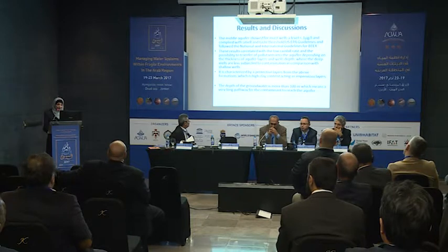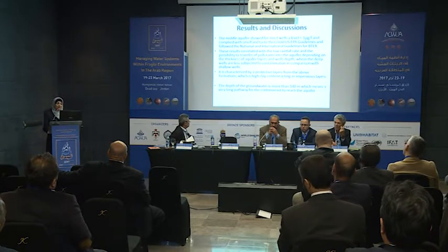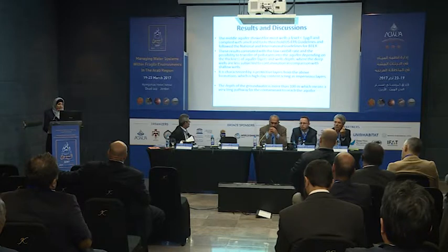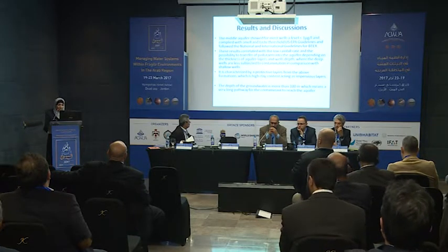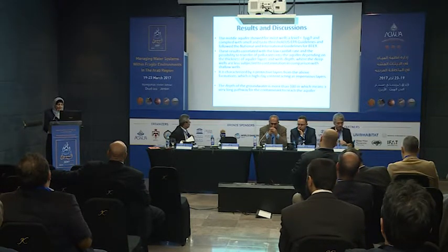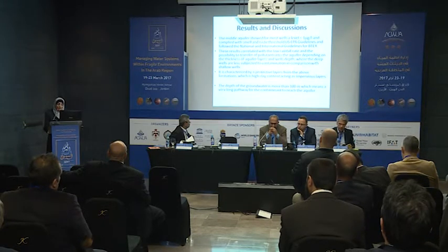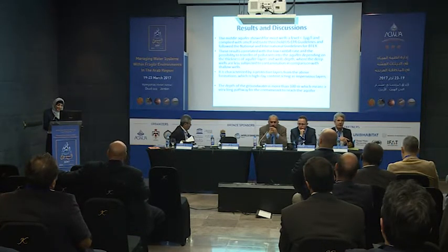Also, the middle aquifer showed low levels, not detectable and below the LRV, and it is also characterized as a protective layer from the above formations, which have high clay content acting as a protective layer. The depth of the groundwater is more than 100 meters, which means a very long pathway to pass through into the aquifer.